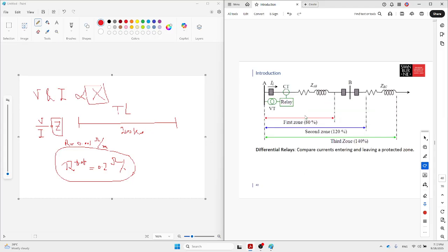So distance relay has three zones. Normal distance relay, the relay can have 5 zones. Okay. So here, as a normal one for your level, only 3 zones. Explain. Zone one, which is the very fast one, we call it instantaneous operation, covering 80% of total transmission line. What's the meaning of total transmission line?